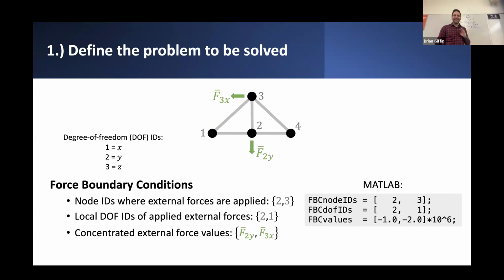All right. So similarly, if we want to impose forces on the structure, specifically on the joints, I can do a very similar thing. I can say which node has a force applied to it, which direction that force is applied in, the x, y, or z directions potentially, and what the value of that force is, where positive values are assumed to act in the positive global coordinate directions. Negative values are acting in the negative y direction or negative x direction.